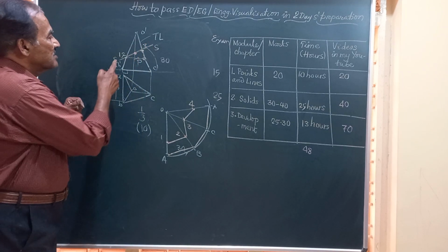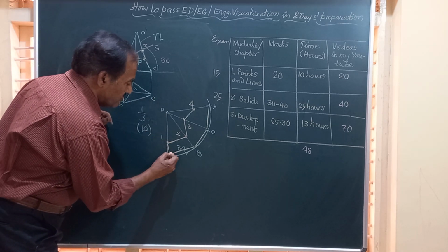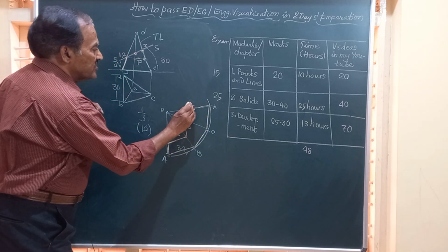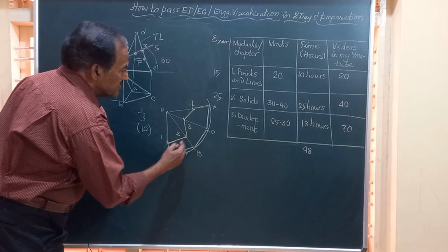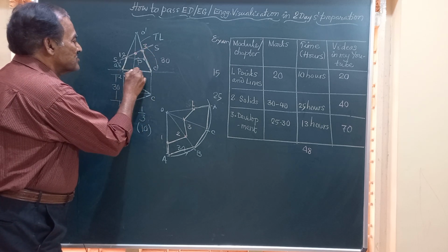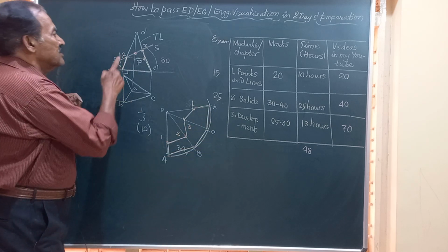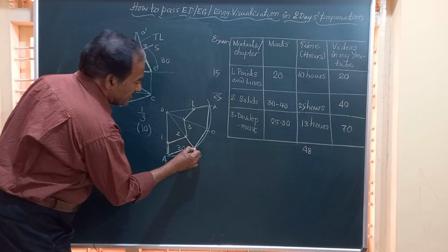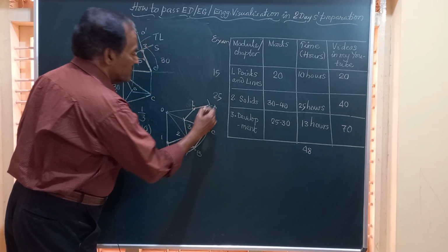Now here, friends, 1 to A, 2 to B is retained. So I have to retain that here. 1 to A, and sorry, it's not 4, it's point 1 only on OA. So 1, 2, 3 only you should have. So friends, all these base edges are not touched by the section plane, and hence the full base should be shown by visible line. Dark line, dark line, dark line. Portion from 1 to A should be dark. 2 to B should be dark line. 3 to C is retained, and again from 1 to A here.